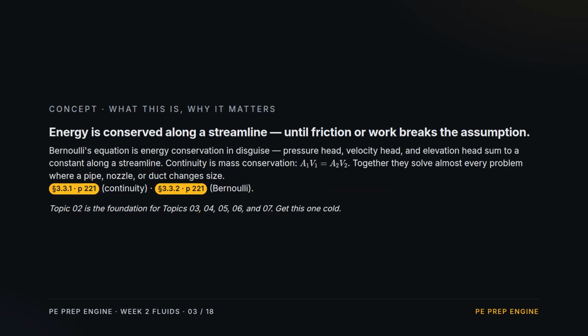Concept. Along a streamline of a steady, incompressible, inviscid flow, the sum of pressure, velocity, and elevation head is constant. Bernoulli, energy conservation in disguise. Continuity is mass conservation. Area times velocity is preserved. These two are the foundation for the next 5 topics. Darcy-Weisbach, minor losses, pump sizing, pump curves, flow measurement.